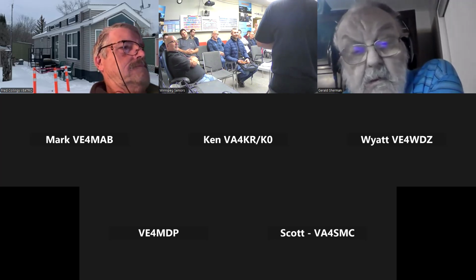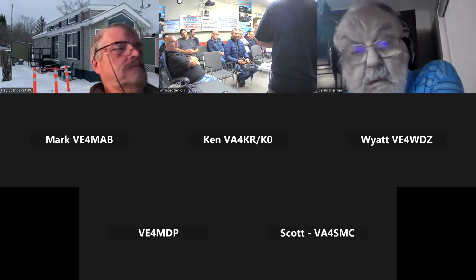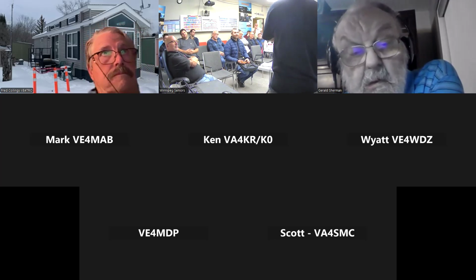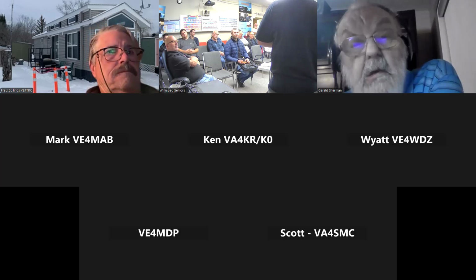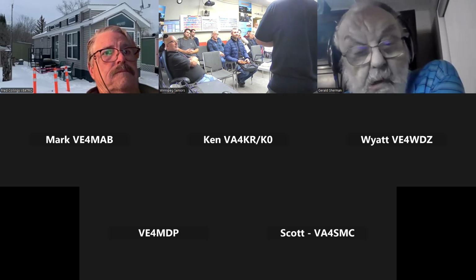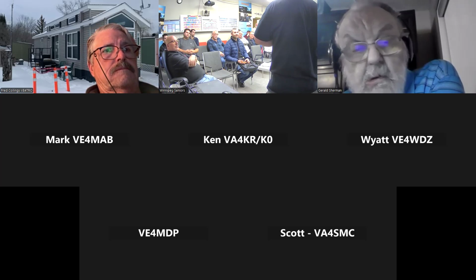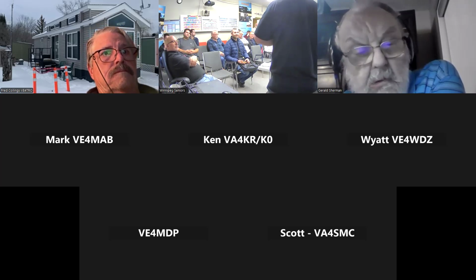This one is only rated for milliamps. 400 milliamp is the max you can measure on current with this, but like I said, I have a clamp meter that I typically use for current. But they do have fuses, internal fuses inside. The fuses are stupid expensive. That 10 amp fuse from Fluke is about $50. But it's a really good fuse.